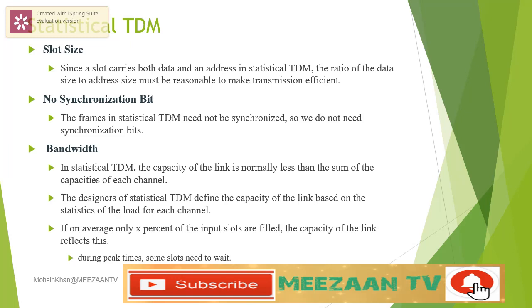Second, the frames in statistical TDM need not be synchronized, so we do not need synchronization bits. Third, the capacity of the link is normally less than the sum of the capacities of each channel. The designers of statistical TDM define the capacity of the link based on the statistics of the load for each channel. If on average only X% of the input slots are filled, the capacity of the link reflects this. Therefore, during peak times, some slots need to wait.